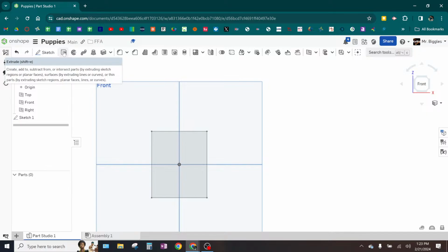If you look at it, this has a profile, okay? And then it gets extruded through a machine to be whatever length they want this piece of metal to be. And so it's actually called extrusion. You guys know what an I-beam is, yes? Yeah? Okay, that is extrusion. You make the I shape, and then you use a machine, you force your metal through it or forge it, and you make it as long as you want. So the most basic feature you will do in CAD software is an extrusion. That is the first feature because it's the most common. So it's right there, and you'll click on it.